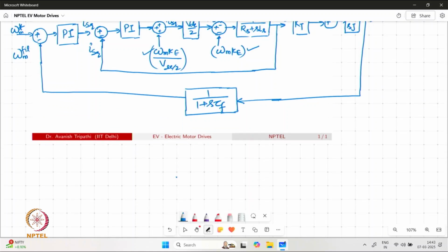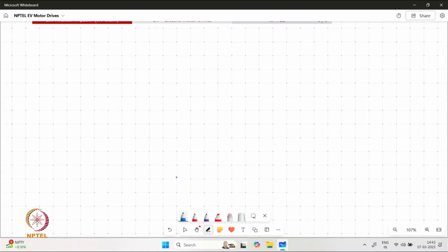Now, going for the other part of the model, which is d-axis model, since we are trying to maintain our d-axis current equal to 0, which means we are neither drawing any reactive power from the supply nor feeding any reactive power to the supply, we are maintaining ISD equal to 0, which is why the reference is considered at this value, and this is compared with the feedback ISD current.